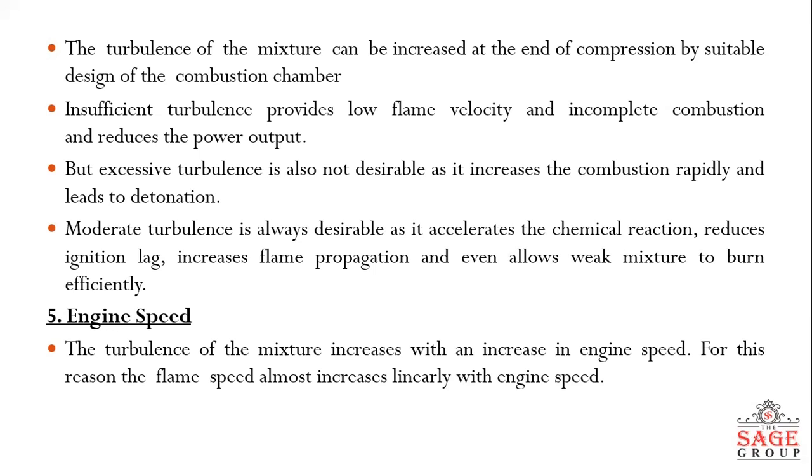The turbulence in the incoming mixture can be generated during the admission of fuel-air mixture through comparatively narrow section of intake pipe, valve opening, etc. in the suction stroke. Generally, turbulence increases the heat flow to cylinder wall. It also accelerates the chemical reaction by intimate mixing of fuel and oxygen. It also helps in burning the lean mixture. However, excessive amount of turbulence may extinguish the flame, resulting in rough and noisy operation of engine.